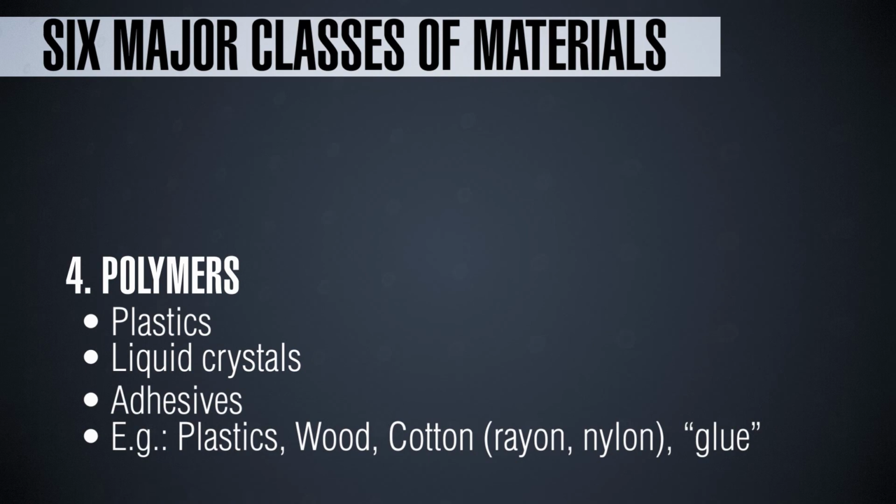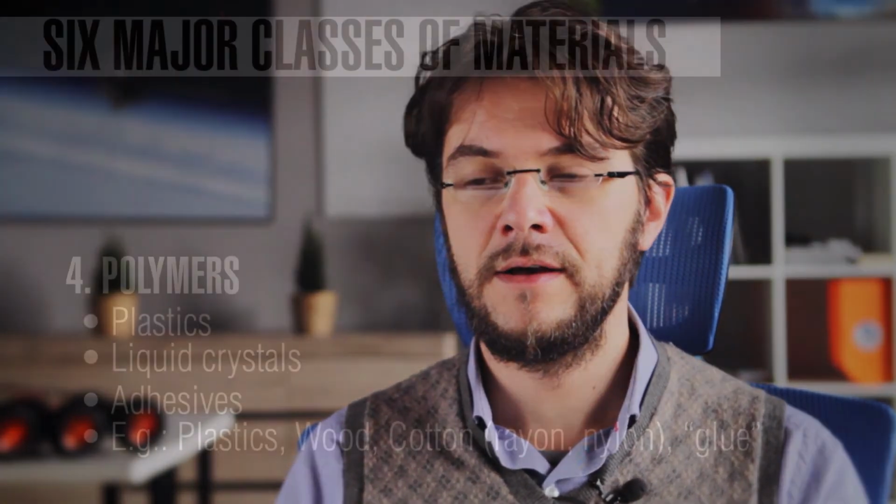So to join different parts, you can use the single components of the macromolecule, which is called monomer, and by certain means, like for example by submitting those monomers to a UV light or to a temperature gradient, you initialize a chemical reaction, which is called the polymerization, that welds together all the monomers, realizing the polymer. In this process, you are able to join mechanically different parts.